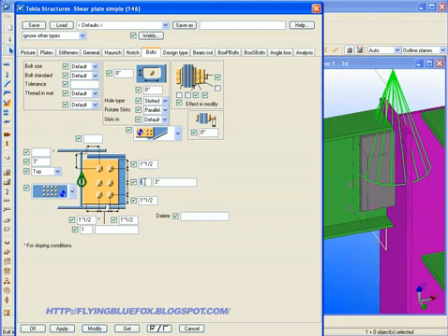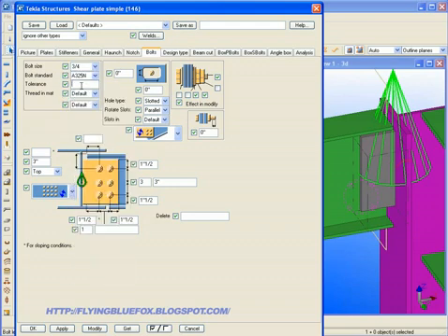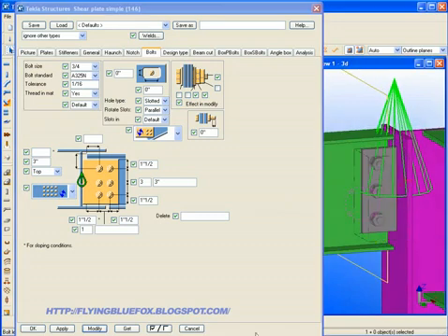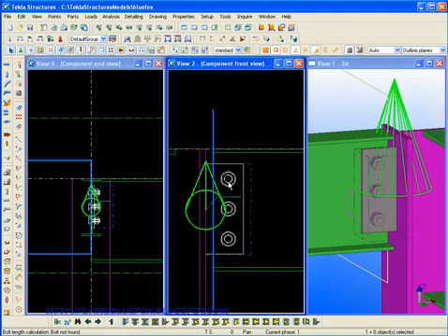Okay, let's change that to 3 and A325 3/4, tolerance is 1/16, thread yes, modify. There we go. 3 row bolt. Apply, OK. As you can see, the front view has 3 row bolts, and if we dimension it, 3 inch, and the edges should be 1.5.